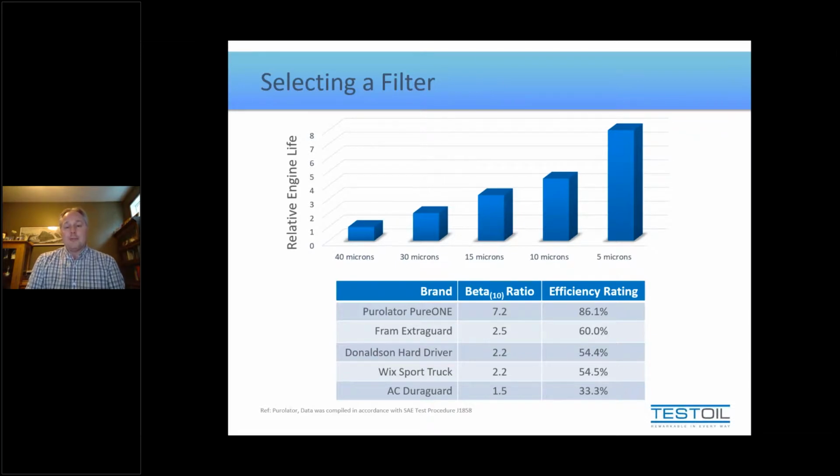Knowing this, I was curious what filter quality I had as my OEM filter for my vehicle. Turns out it was a 10 micron absolute, and it was a 2 micron nominal. So you could say that by comparing it to a Fram, I was either comparing a 2 micron nominal to a 10 micron nominal, or I was comparing a 10 micron absolute with a 40 micron absolute. Really the easiest comparison is to keep the micron ratings the same and say my OEM filter is a 10 micron absolute, whereas the aftermarket is a 10 micron nominal.